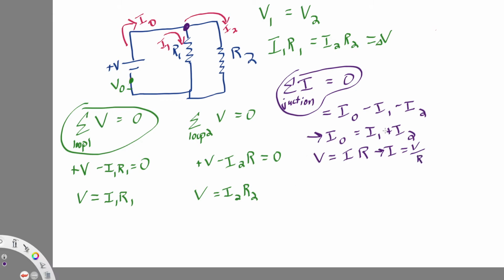And so we can rewrite this statement as saying the overall voltage divided by the equivalent resistance is equal to, so I1 would be the voltage over resistor 1 divided by the resistance of 1, and then I2 we could write as the voltage lost over resistor 2 divided by the resistance of resistor 2.